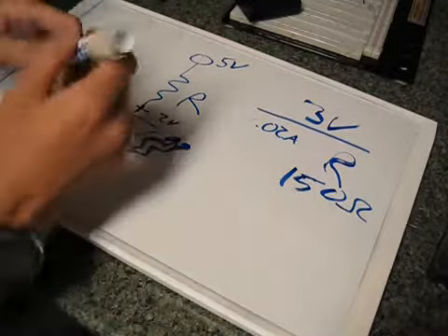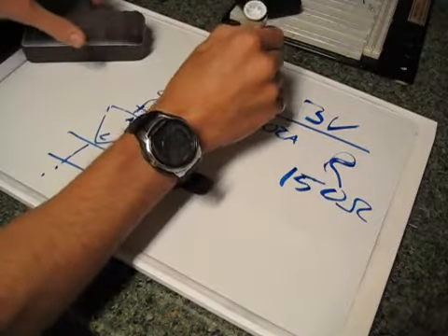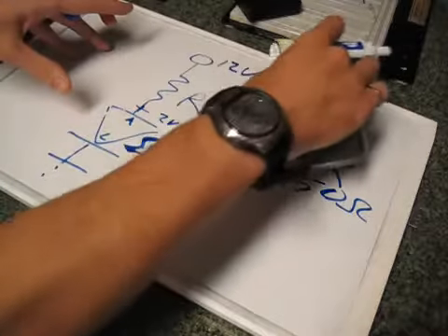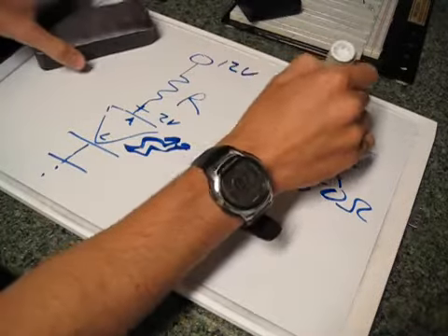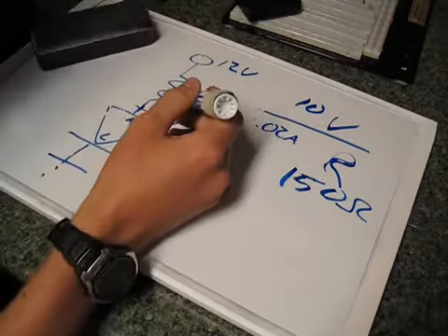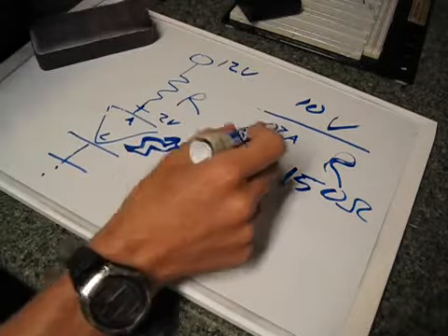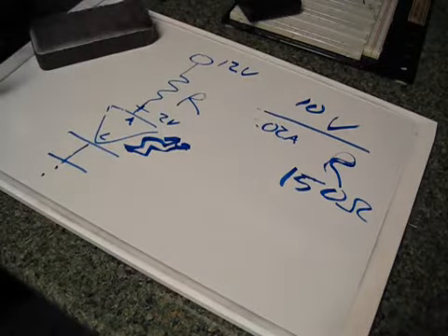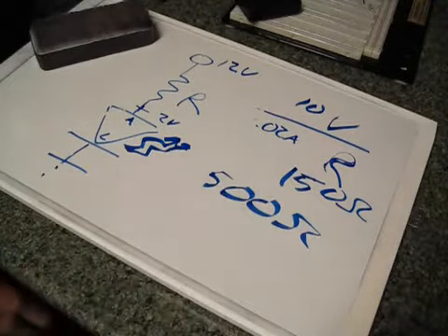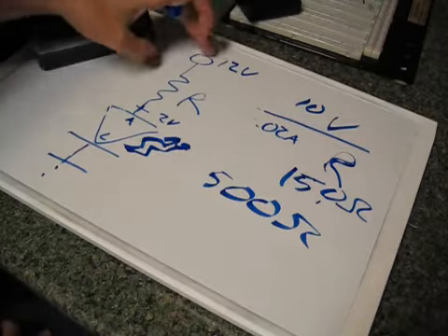But that's basically how to calculate the resistance. If you're in a jam, let's say suddenly this changes up here to 12 volts and you're working in your car and you want to turn on an LED. It's the same thing. You go 12 minus 2, which changes this value to 10 volts. Current stays the same. That's why they call it a current limiting resistor, because we need to limit the current through the circuit to 20 milliamps at all times. So 10 divided by 0.02 gives us 500 ohms. It went from 150 to 500 just by switching from 5 volts to 12 volts.